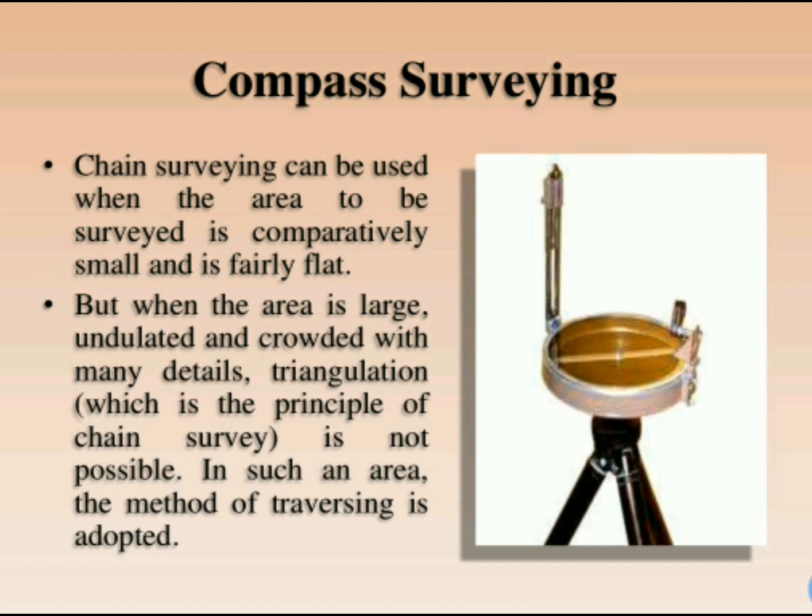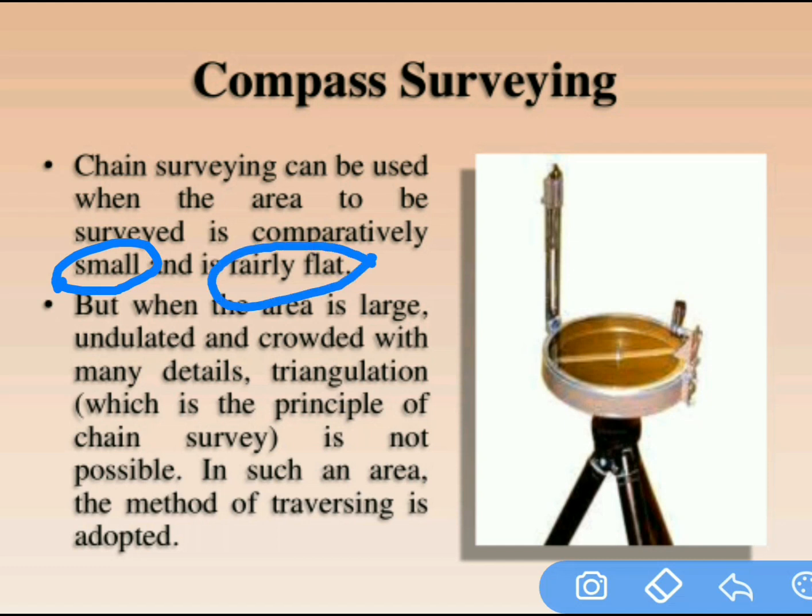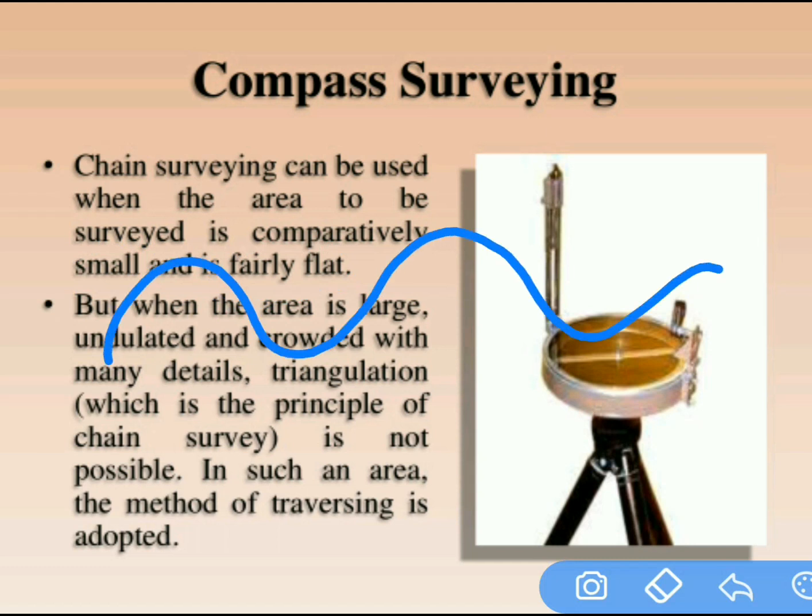Right. So here, when is chain surveying suitable? If the area is small and fairly flat, then only chain surveying is suitable. What is the meaning of that? See, if the ground is uneven, then we cannot use a chain.